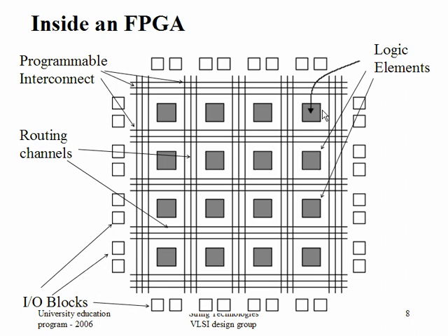And programmable interconnects are those pieces where you connect the wires, the routing channels, appropriately. What I mean by appropriately is, I am writing some piece of logic where the output of this logic element should go to the input of that one. So I'll program it this way. I will show those things in the Spartan 3 inside view.